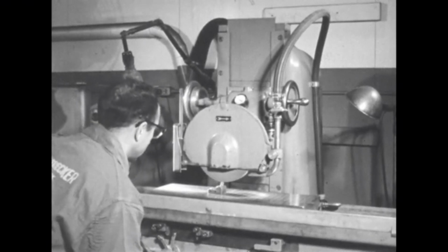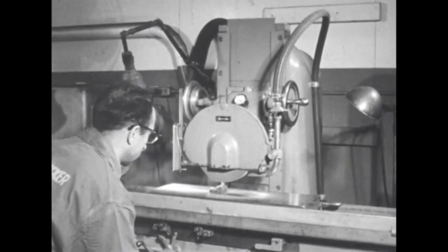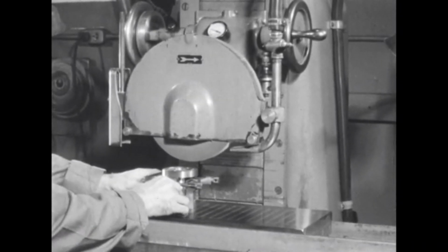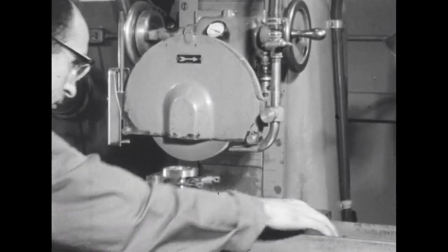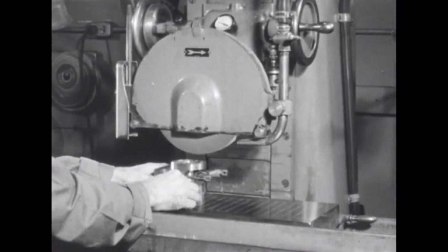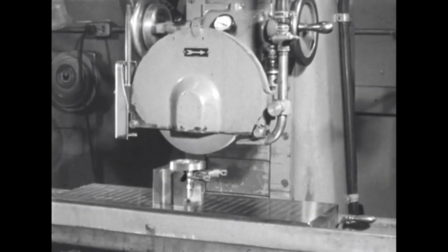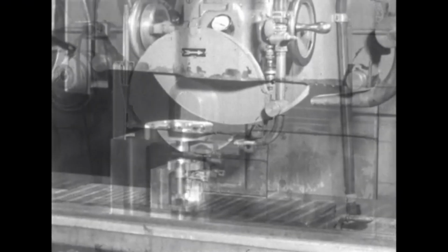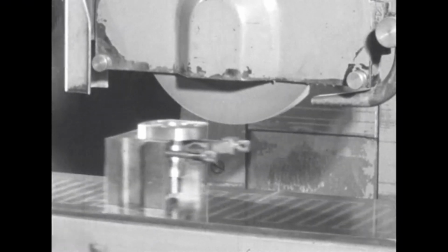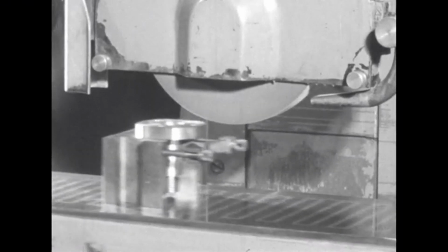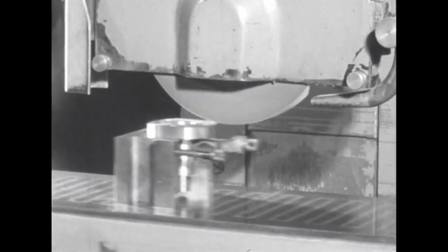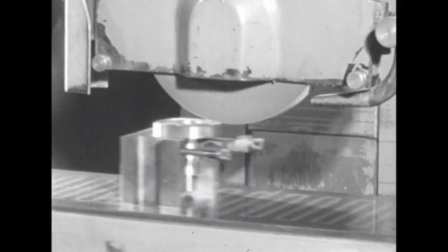Because most workpieces are of iron alloys, surface grinders are usually equipped with a magnetic chuck, which can be magnetized to hold or demagnetized to release the workpiece. The magnetic chuck with the workpiece is moved back and forth under the grinding wheel. At the same time, it moves away from or towards the operator until the entire work surface has passed under the grinding wheel.